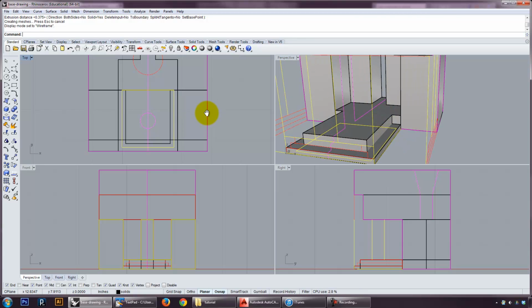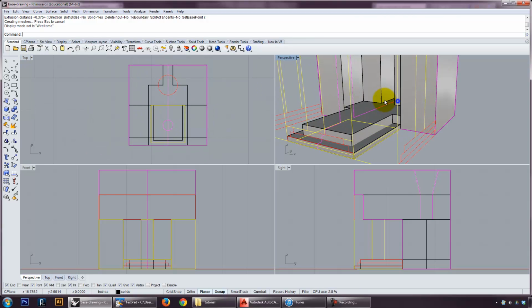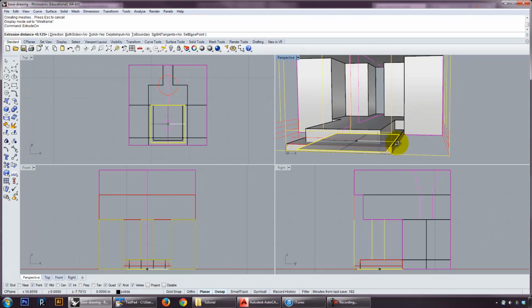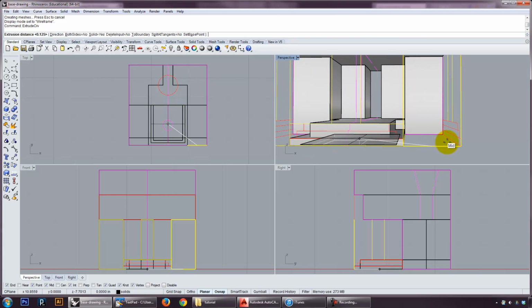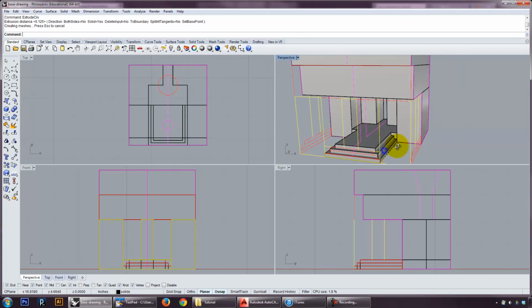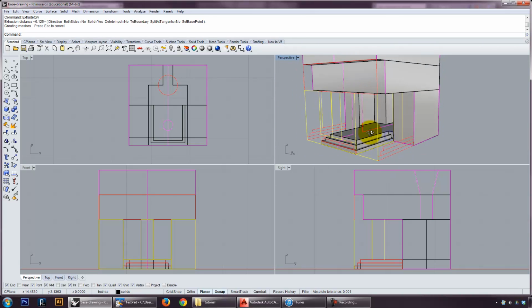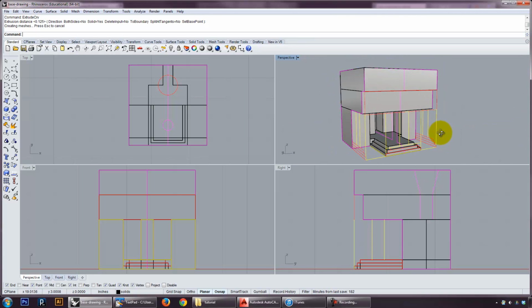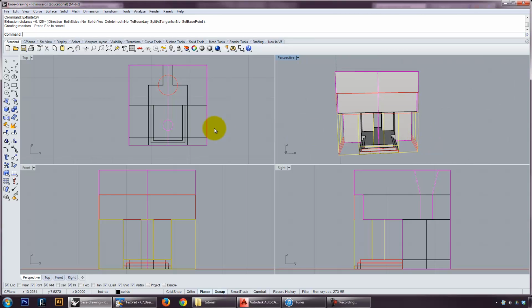Notice these different view modes, like the wireframe makes it easier to select lines, but the shaded view makes it easier to kind of find the snaps I want from the solid. So you're always changing your perspective, you're always changing your view mode to be optimal. So now if I do that, I've got these things nested in each other, it's really clean. Okay, not too bad.